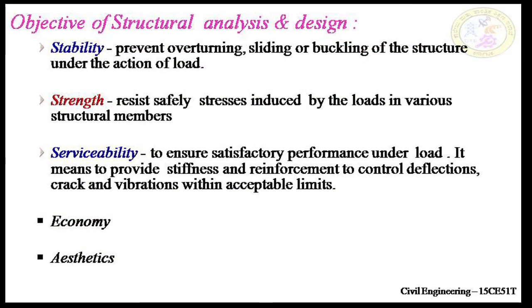Now, coming to the objective of structural analysis and design. Any structural analysis and design problem should satisfy stability, strength and serviceability criteria together with economy of the structure and also aesthetics. It should provide stability to prevent overturning, sliding or buckling of the structure under the action of the load. It should give strength to resist safely the stresses induced by the loads in various structural elements.